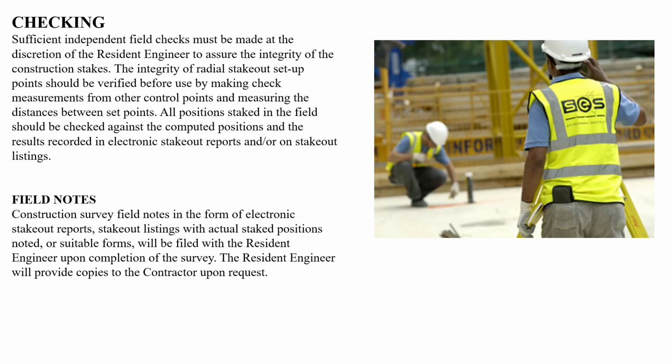All positions staked in the field should be checked against the computed positions and the results recorded in electronic stake-out reports and or on stake-out listings.